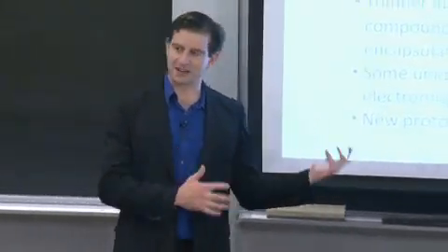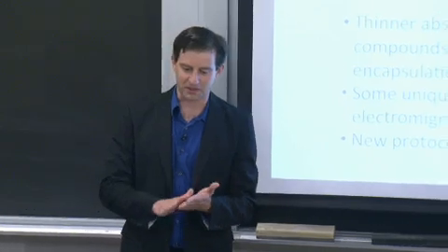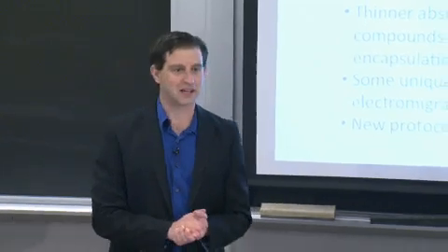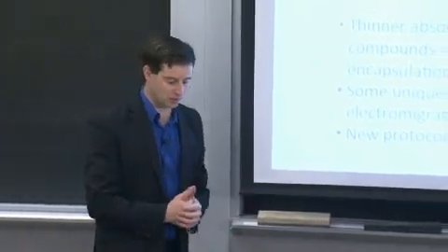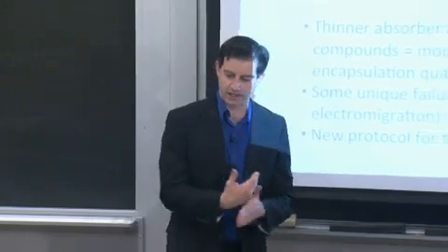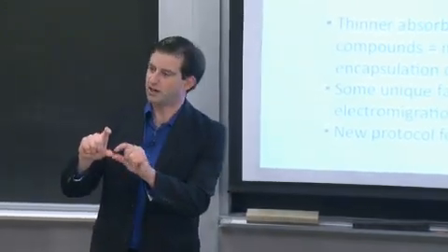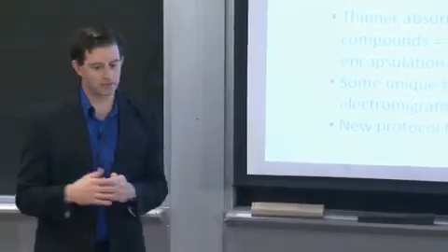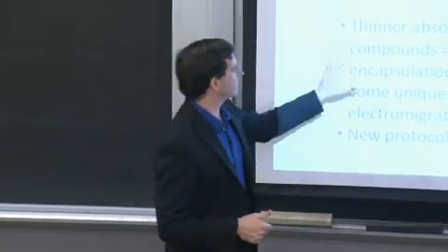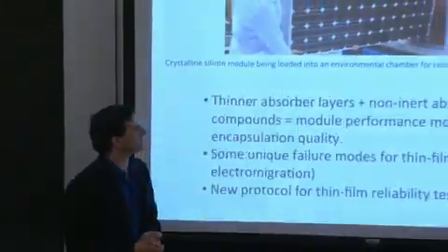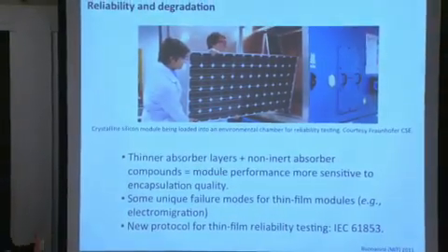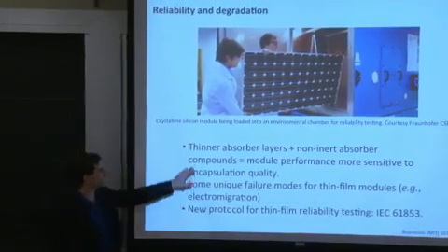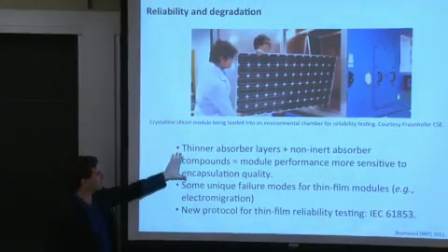But now if you take a fairly reactive material, a thin film material that might react with air or might react with water, and it's so thin that these rusting modes or reaction modes, the weathering modes, can really impact a large fraction of the thickness of your device. Now you become a lot more sensitive to accelerated degradation. Now you become a lot more sensitive to the elements, and this includes both oxygen and water. So if the ambient is able to penetrate through the encapsulant and get to the active absorber material, you may have accelerated degradation of module performance as a result.